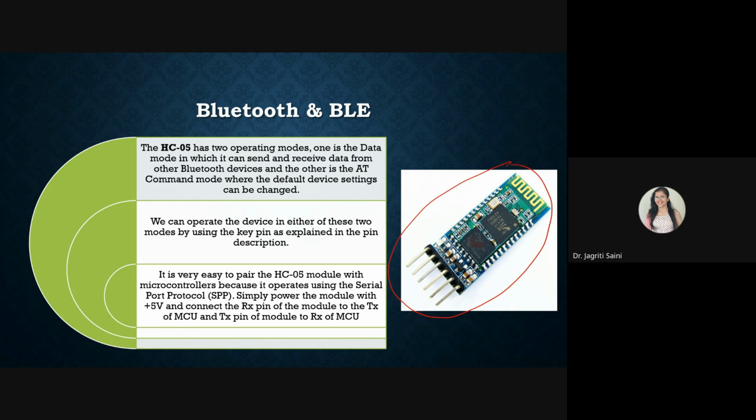One amazing thing about this Bluetooth chip is that although this is a very mini chip, it can offer you UART based communication through your transmit and receive lines. And similarly, it works on AT commands also. This first pin allows you AT command based communication. If anyone has worked on communication modules earlier, or has learned about the communication system that we follow in GSM, etc., you might have heard about AT commands. These are very important commands that we set up for the interface between two communicating modules.